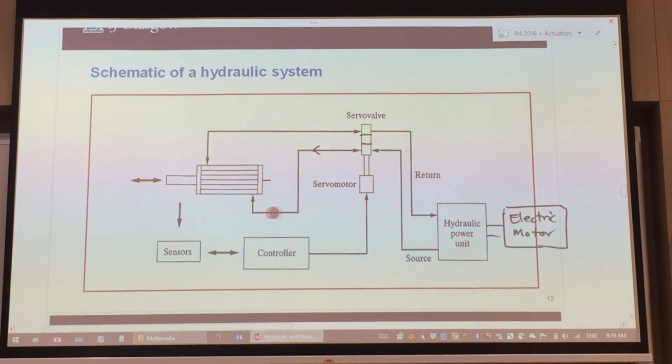So it's going to energize it and move the piston to this left side. Energize it and then it's going to flow back that way. If you move the other way around, that is, energize it such that this one is the one moving that pressure, then you will retract your cylinder to the right-hand side.